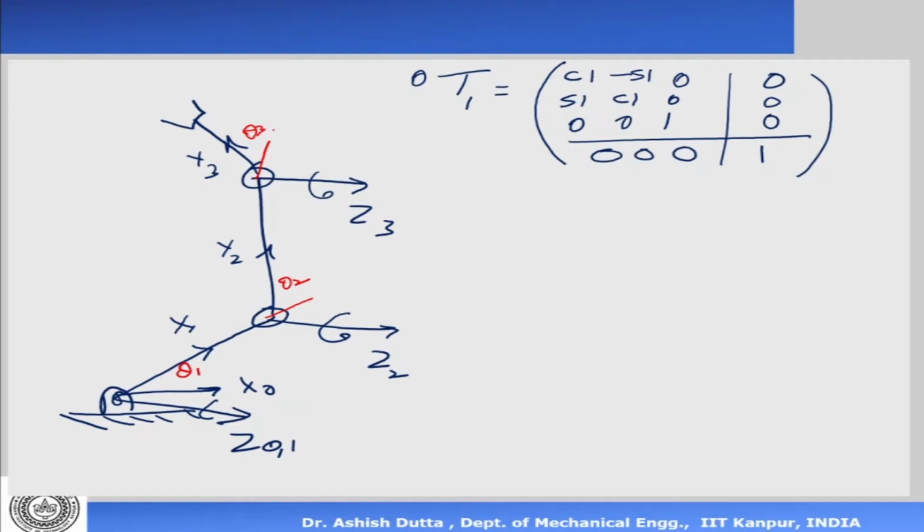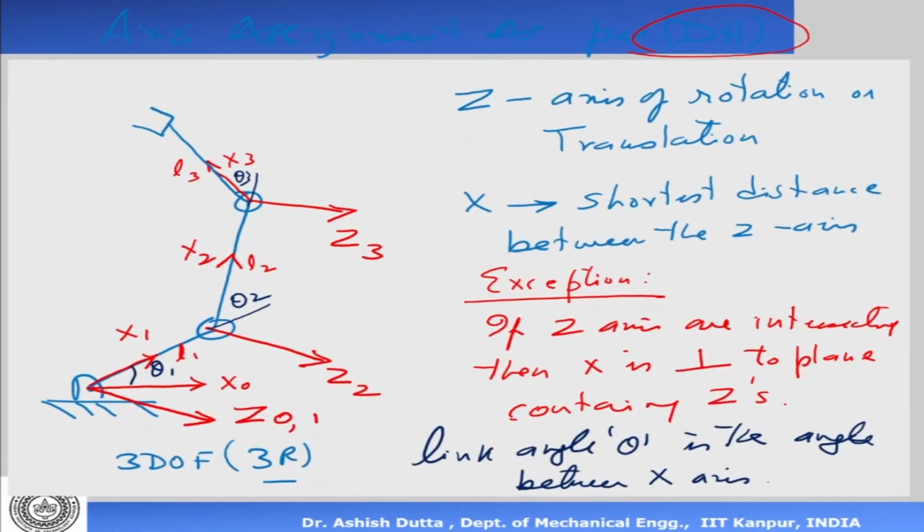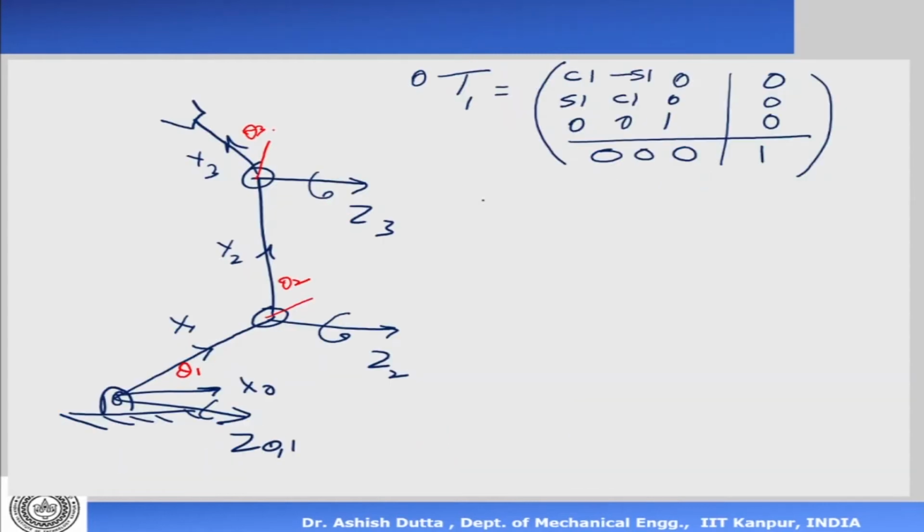Now if you can connect the dots, so what I just said some time back, that in the DH notation, the z-axis is the axis of rotation. So you'll always get Rz theta. This axis will always be the same. Okay, that simplifies matters. So this is the first one that relates the first frame to the 0 frame.